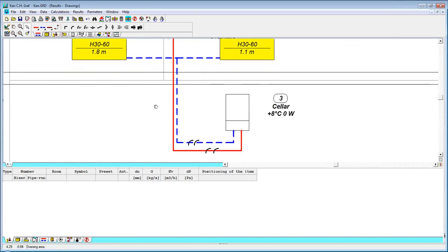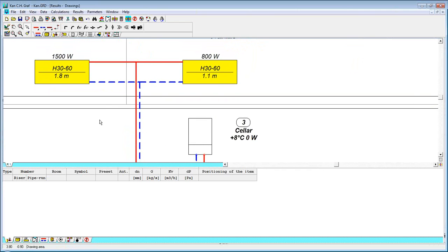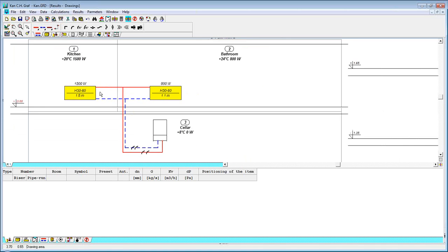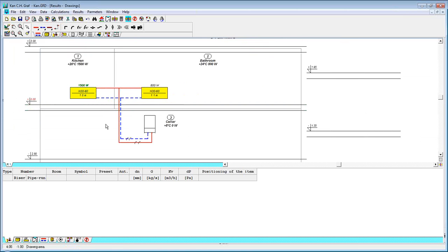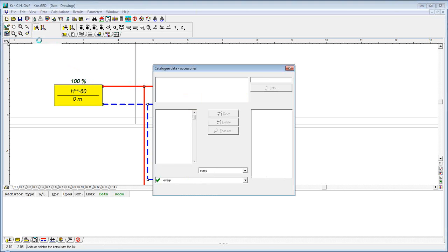And as I told you, we have forgotten the valves, and I expected some errors with the problems of balancing, maybe because the system is pretty low and the program has got some criteria, so after an analysis it occurs that here this problem is not so big. However, to show you how it should be done in a proper way, let's also look for a valve, radiator valve.